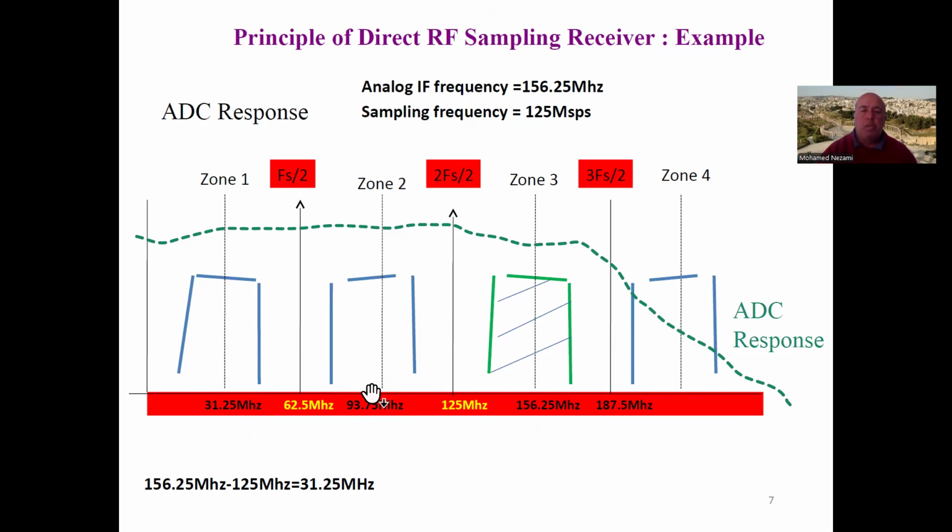Second one is here. So now in the DSP, if you want to rotate this to baseband, you could program your numerical control oscillator at the negative frequency of this, or the negative frequency of this, and then multiply it with the incoming signal. You've got a complex sample multiplied by a complex NCO, which is just sine and cosine, just like a quadrature down converter, except it's done in the DSP.